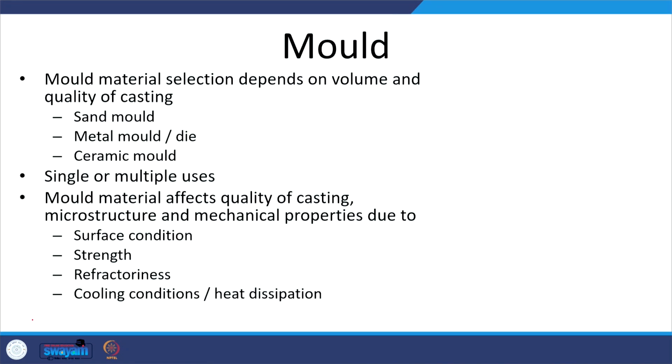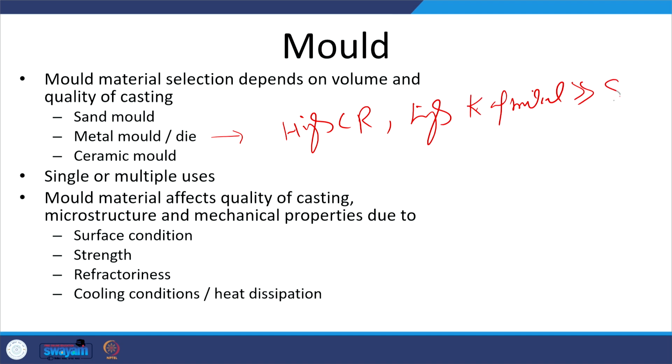But if you see the feature related to the high cooling rate offered by the metallic molds, due to the high thermal conductivity of metals as compared to sand, the high cooling rate means lesser solidification time.